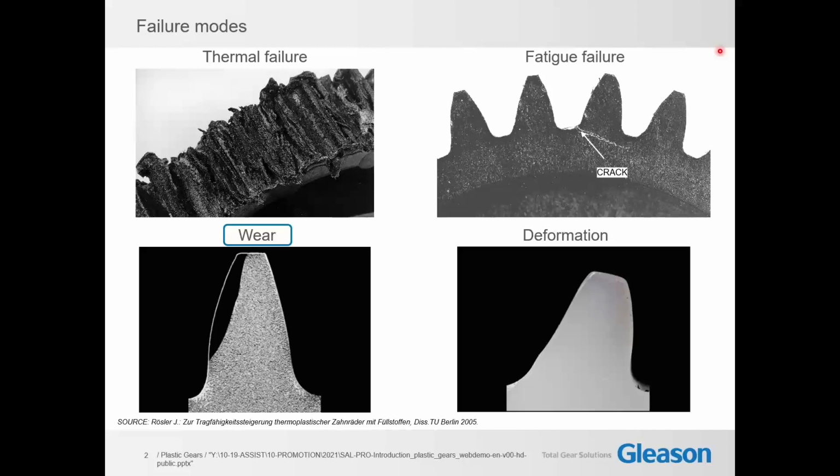The main difficulty is that wear is a matter of the material pairing. It is not only influenced by the material of the gear that is of interest, but it is also influenced by the material of the mating gear and even the type of lubricant. If there's contamination of the lubricant, then it is, as a fourth component, of course, depending on the contamination.